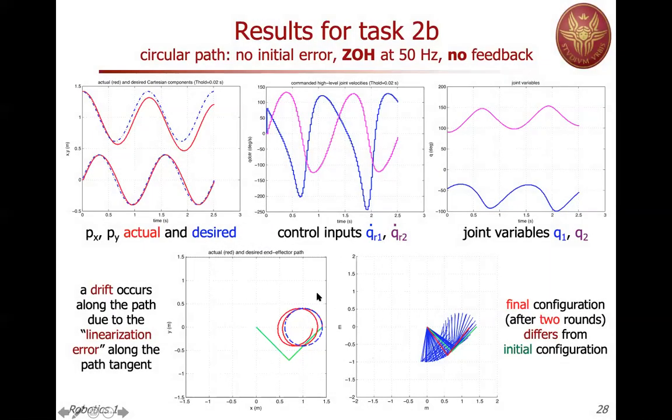If I continue, I don't know if this is drifting forever, but certainly this is not what we would like. In fact, we have not activated the feedback part here, relying only on the feed-forward. If we cannot update the feed-forward fast enough, this is another big reason for closing a feedback loop, for moving from planning to control.